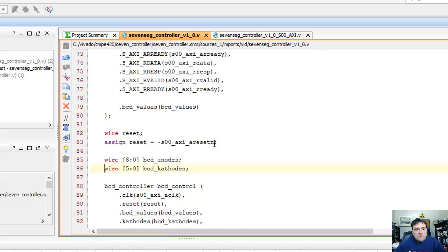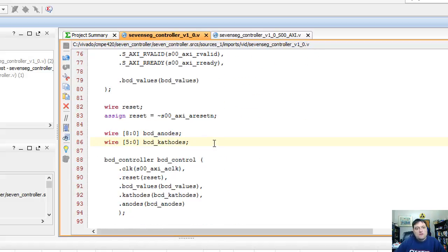And what I've done is I've made it where I can simply write a value into a register, and this BCD controller will suddenly get input on the values, and it will do its normal job of mapping those BCD values into our 4 7-segment displays. It will manage the clock. It will drive the clock values to be whatever they did before. It does everything that it did before. Only now, instead of having the driver do that, the values come from the AXI bus.